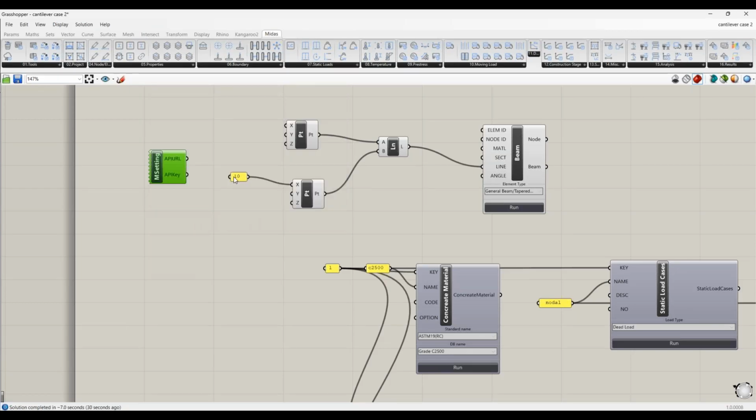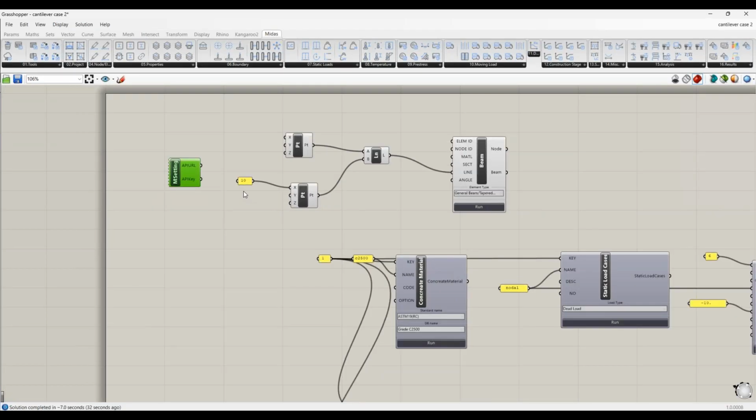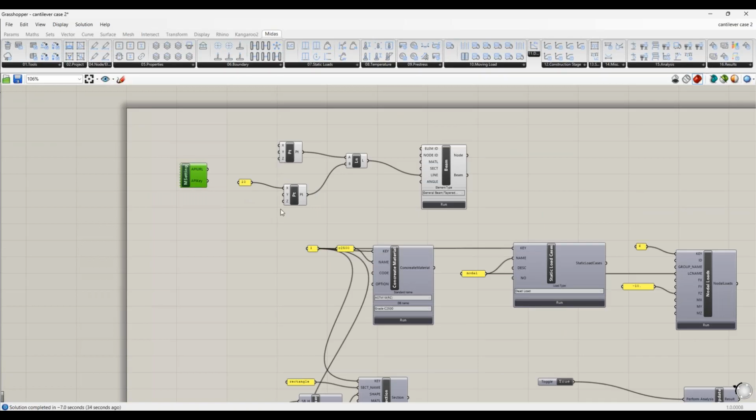Then, here we have mentioned first, let's say there is a line element which is connected. The first node is at the origin, so it doesn't require any coordinate, whereas for the second we are specifying a coordinate, let's say x is equal to 10. With these two nodes, I'm going to create one line element, which is creating the line between the two points.